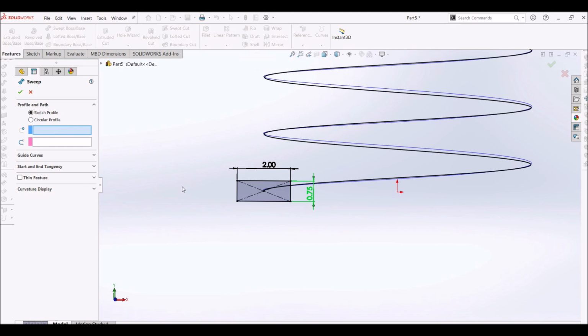So we're going to select this little square, and you need to select all the edges of it, and it needs to be a closed entity. That's very important. Do you remember from the last class, a closed entity is a complete loop. So we're going to click every edge of this square or of this rectangle,